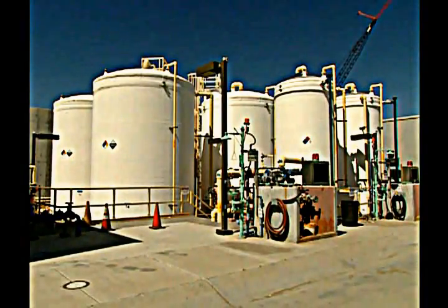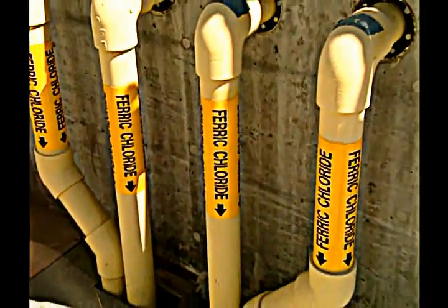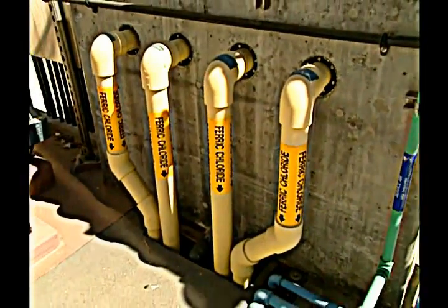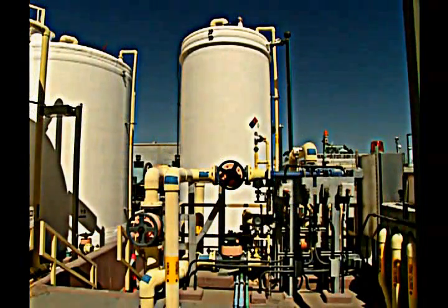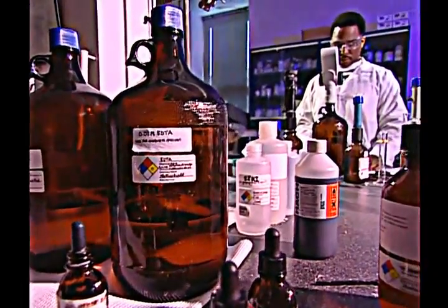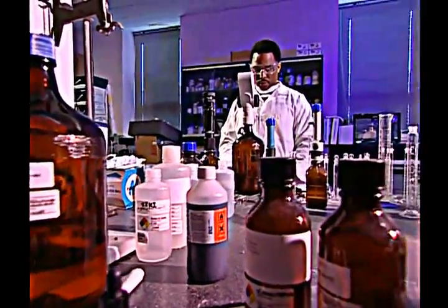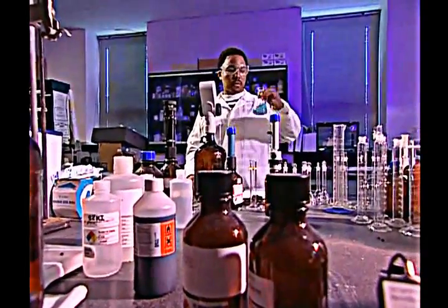Polyaluminum chloride and iron salts such as ferric chloride and ferric sulfate are alternatives to alum, and they operate over a wider pH range. The chemists have gotten more creative and they've developed compounds that are advanced in various ways. You can have polymerized aluminum salts, you can have blends of the inorganic coagulants, the alums and the ferrics. They all have their little benefits that will improve the clarification process.